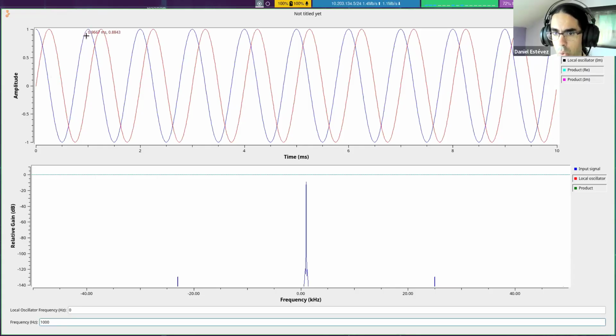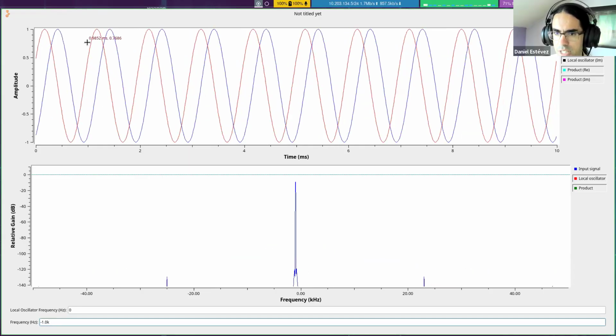This is what, when you plot these things in the complex plane, not just versus time, makes the function rotate counterclockwise. If I change this to a negative frequency, so minus 1000, you can see that the order of these things is swapped. Now the red comes before the blue. So this is a negative frequency. That is also a reason why we can distinguish positive and negative frequencies, because we have two components, real and imaginary, and one of them needs to come before the other one.